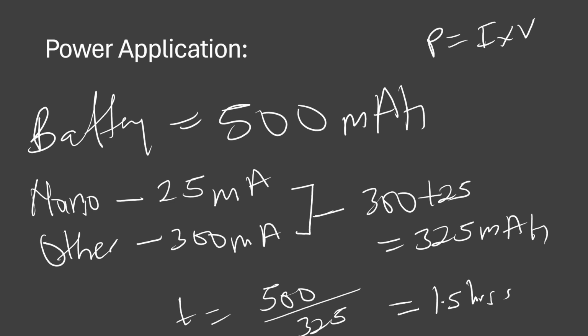So the better battery you select, let's say you get another battery of 5,000 milliamp hour, this is promising you more hours of run without the battery running down. So you have to know how to do this calculation so that you know how long your battery will be able to sustain the circuit.